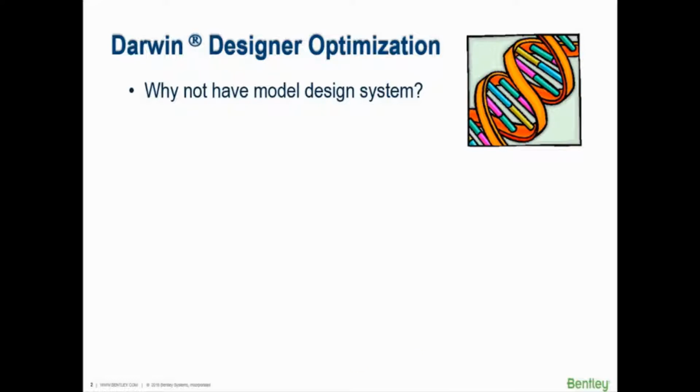Well, instead of solving a system of equations as you do with hydraulic or water quality analysis, you're solving a mix of equations and inequalities, which really kind of messes up the math. And there's some judgment involved in it too. Then you have some parameters that are like continuous variables, like flow and pressure, and some that are discrete variables. Have you ever tried to buy a 17.48-inch pipe? Well, the design might call for that, but that doesn't exist.